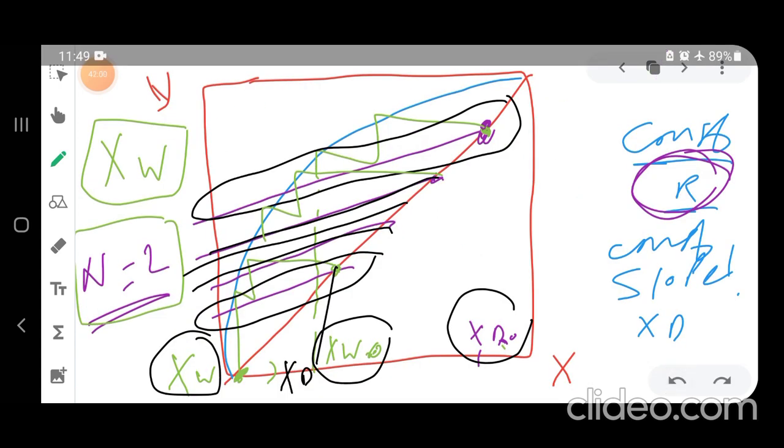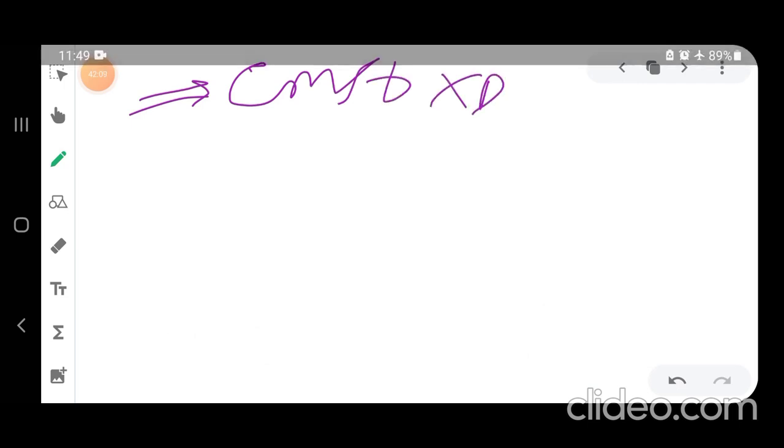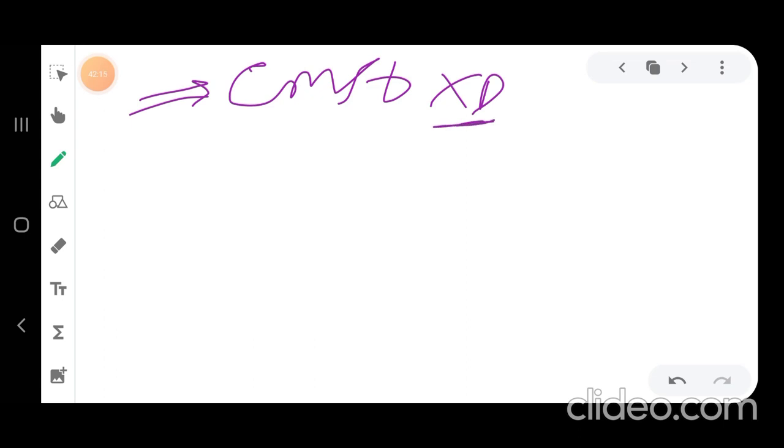The last thing here is, what if we have a constant xd? Batch rectification with constant xd. Since this xd is constant, we can make a very good assumption that is highly valid, that we can see the instantaneous composition of D is equal to the average composition that we are going to collect at the end of the day, because xd is constant, it will not change.